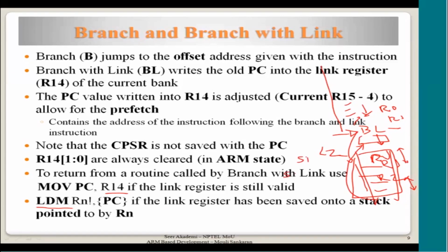Okay, store whatever registers you mention in the register list to the stack, somewhere in the stack. You know that maybe R13 you may be using as a stack pointer, or any other register. You put them into the stack. Suppose it is going downwards, you keep on putting them. And then when you are done with your function, you will be writing an LDM to say copy back